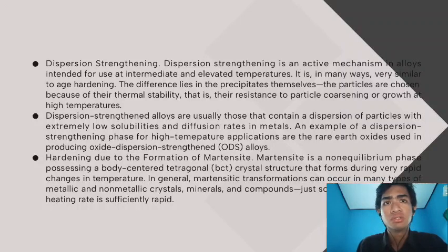Next, dispersion strengthening of copper alloys for hardening, controlling grain size, and providing softening resistance is exemplified by iron particles in copper-iron alloys C19200 or C19400, and in aluminum bronze C61300 or C63380.